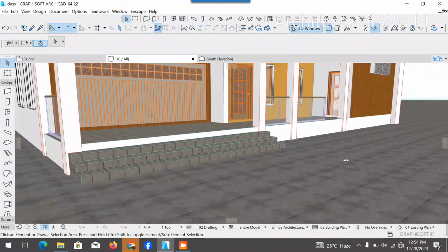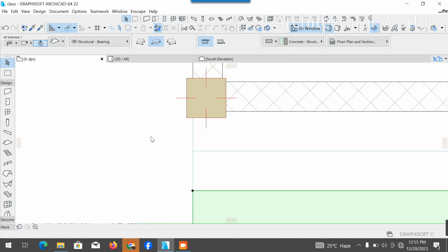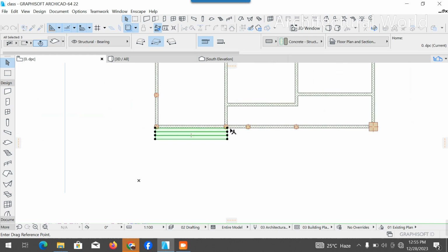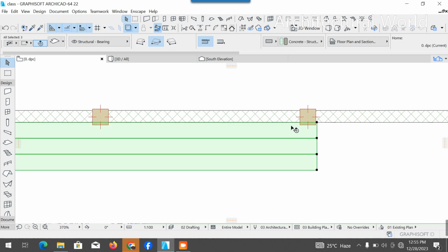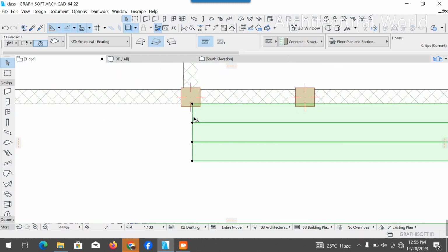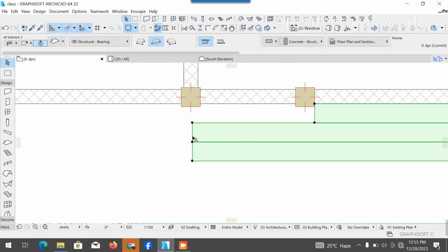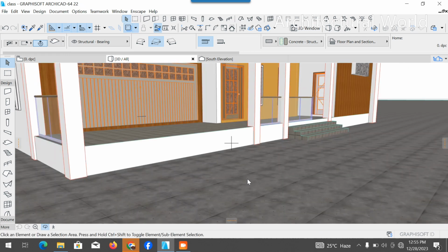Oh, my bad. I forgot that this is a garage. What we need here is a ramp, not a slab, not a staircase, a ramp, because car is going to drive through. Okay, so we're just going to move these 3 steps that we just created. We're going to move them to this way. Then we reduce all 3 of them to this spot, reduce this to this spot, we reduce this to this spot. Okay, let's see that on 3D.